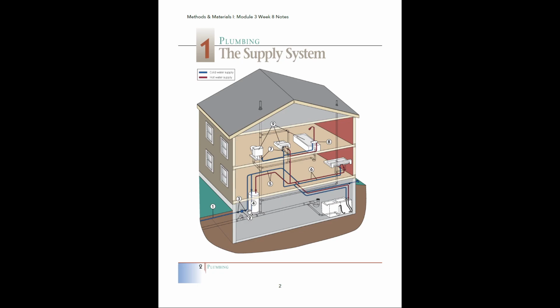So if any of you live in a house that has a tank water heater like this, you're probably familiar with taking a shower, and if you're in the shower for too long, eventually the water gets cold and you lose all your hot water. That's because you have this tank water system that can only distribute the water that has been heated up inside it. As you deplete that water supply, it has to bring in more cold water, but obviously it takes time to heat that cold water up to the temperature that you want. If it's not heated up, it can't give you any more hot water, and you end up just getting cold out of the hot water line.